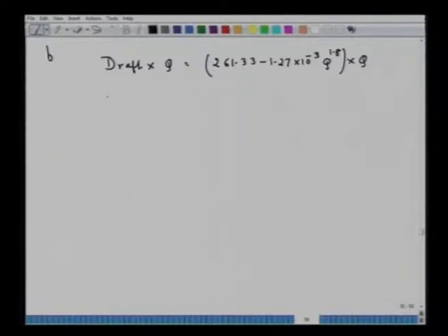So I have to take the partial differentiation, that is dH upon dQ, if this value is equal to H, horsepower. I do this differential and I put it equal to 0, then I will be getting Q equal to 505.195.